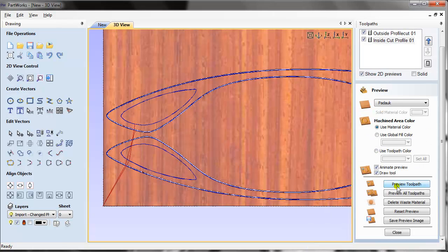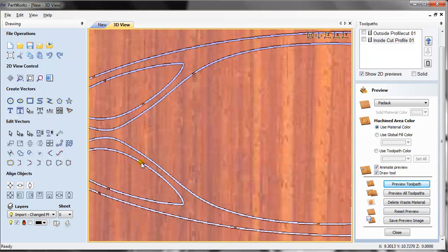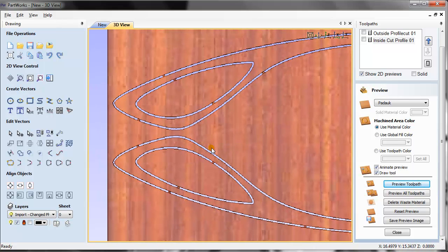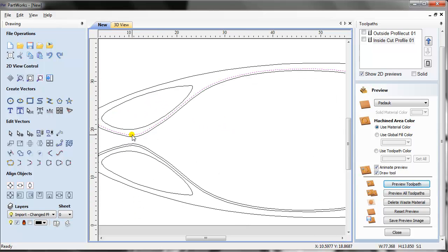Say okay here. I'm gonna preview that toolpath. So as you can see, it's been chopping perfect, nice and clean, holding two little tabs here that I expected. So far I'm done with this. Now these two little lines here are gonna be the groove here. I'm gonna select them both, holding the shift button, and I'm gonna click on the groove vector.